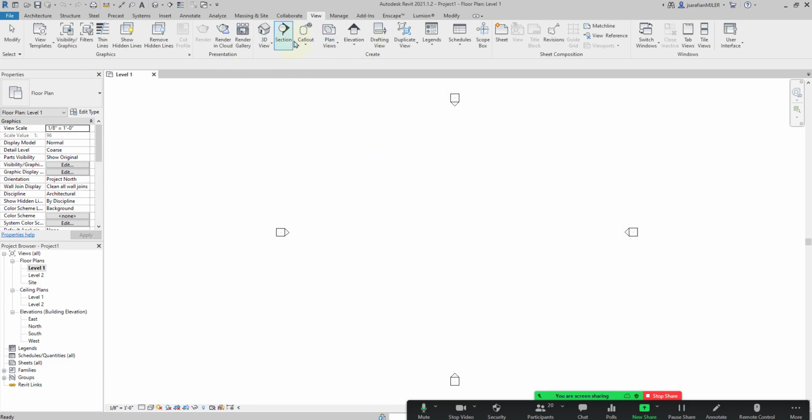And then, yeah, creating different views. So if you want a 3D view, we can go into that. We can create a new section, so this will cut through the project, and we can locate that. Callout can be drawn. Plan views, so there's other types of plan views. So area plans, if we want to have a designated plan that identifies the area of the project, square footage, that can be calculated here.